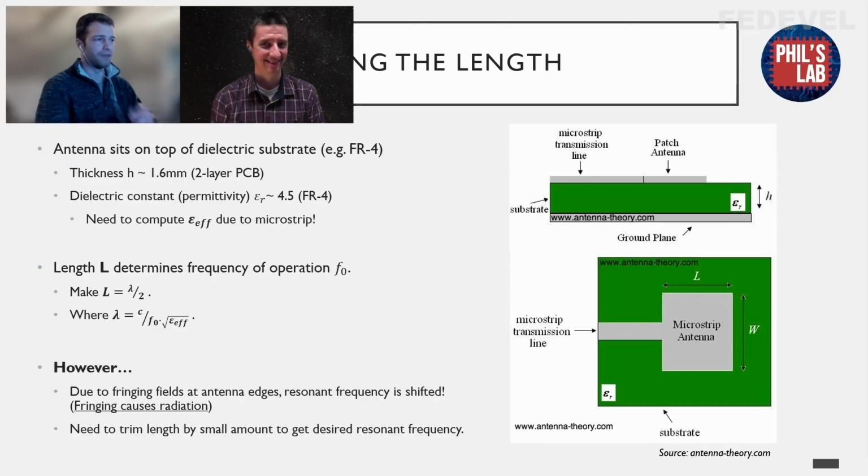I mean, also modern phones are probably in that kind of order of magnitude. So the thing is, you can't just use that calculation. That seems a bit too easy, especially for antenna design. We have fields underneath the patch antenna once we have, for example, a standing wave there, or voltage applied, but also we have fringing as usual. So we don't have just field lines going straight down, but also fringing at the sides.